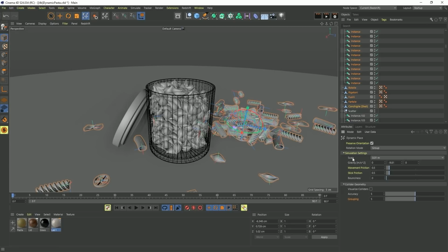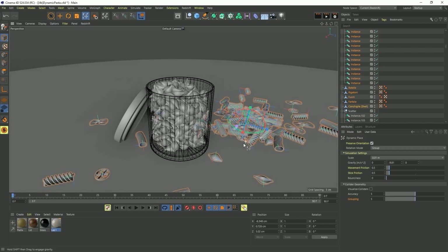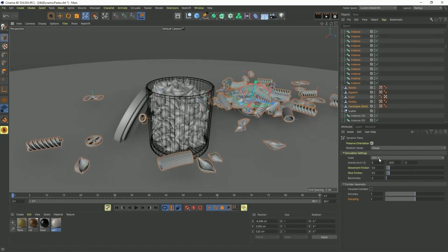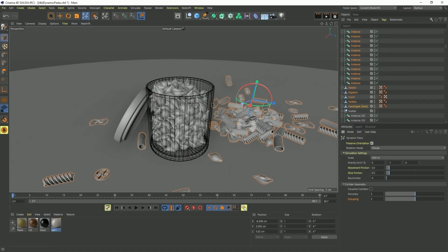In addition to that, we've got regular world gravity on here, but if things are bouncing around too quickly, if they don't settle in, if they're passing through each other a bit, something I like doing is lowering the gravity to be relatively low. And now when I hold down Shift and drag, they will gently fall to the ground, and there's not going to be quite as much randomness happening. Everything gently falls. So a really quick and easy setting to change as well.